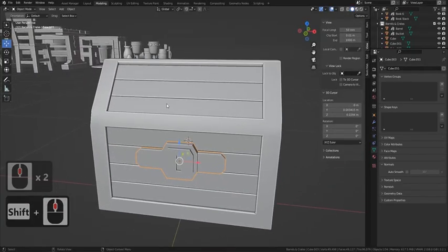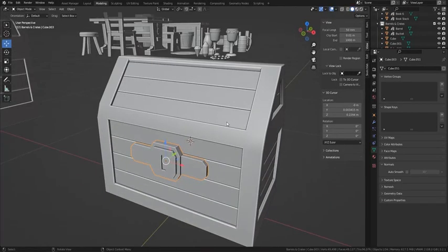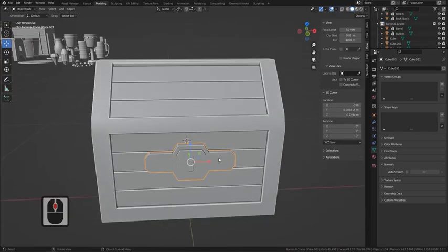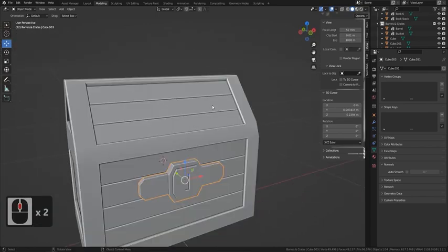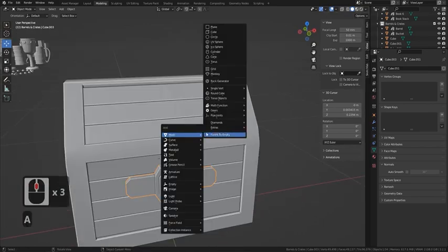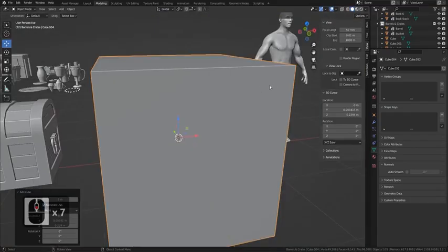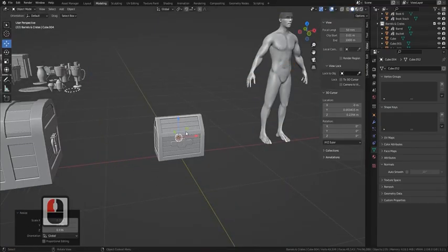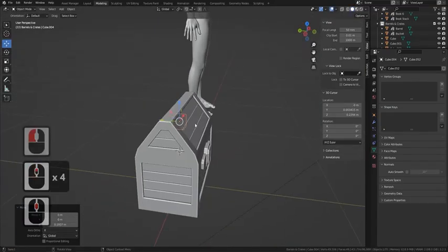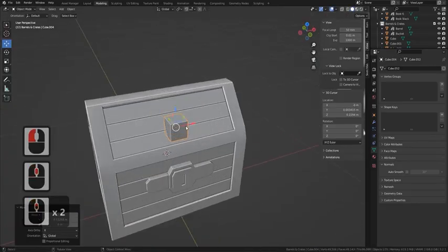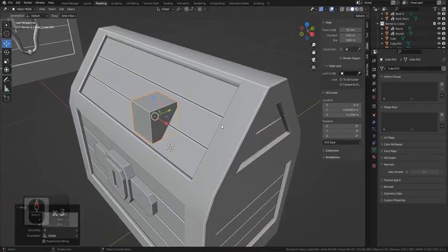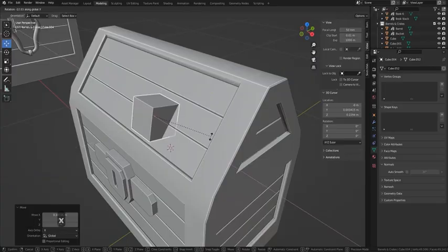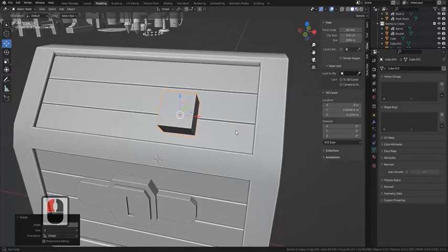Alright, so now let's make these actual kind of metal type straps that are going to go around here. So we'll make the top parts of them. And I think on this, we'll actually make them leather as well or something like that. So let's do that. So first of all, we'll make the top part. So Q, S, and then we'll bring it up and pull it out. And we'll put it to the place where it wants to be, which is roughly around there. And then we'll rotate it. So R and X, rotate it round.